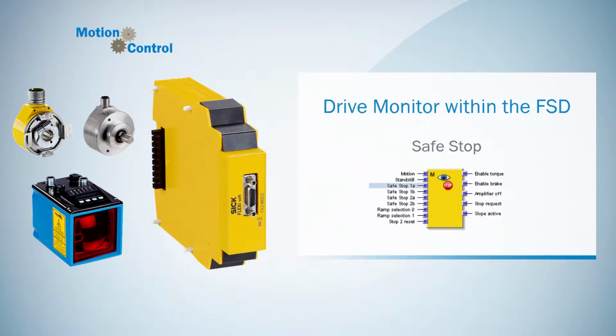The input saveStop 1A as well as the optional input saveStop 1B are normally high. If one of them goes low, then they trigger the function saveStop1, which induces the brake operation of the drive via an emergency stop ramp. This brake operation is monitored from the drive monitoring device. When the current speed is below the standstill speed, then the energy supply of the drive will be disconnected.